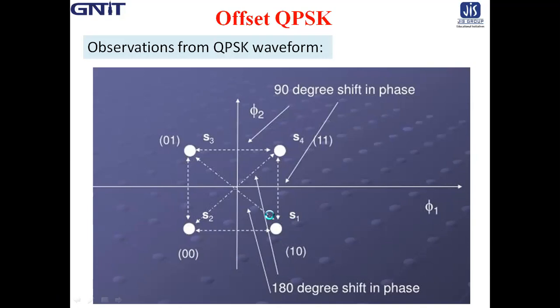So situation 1 occurs to a much lesser extent. Situation 2 can be of particular concern when the QPSK signal is filtered during the course of transmission. Specifically, the 180 degree and 90 degree shifts in carrier phase can result in change in the carrier amplitude, thereby causing additional symbol error in detection.